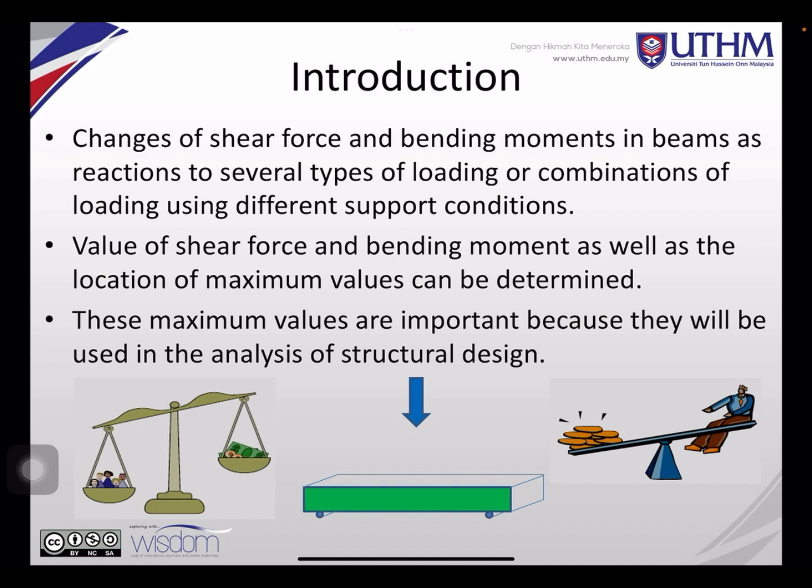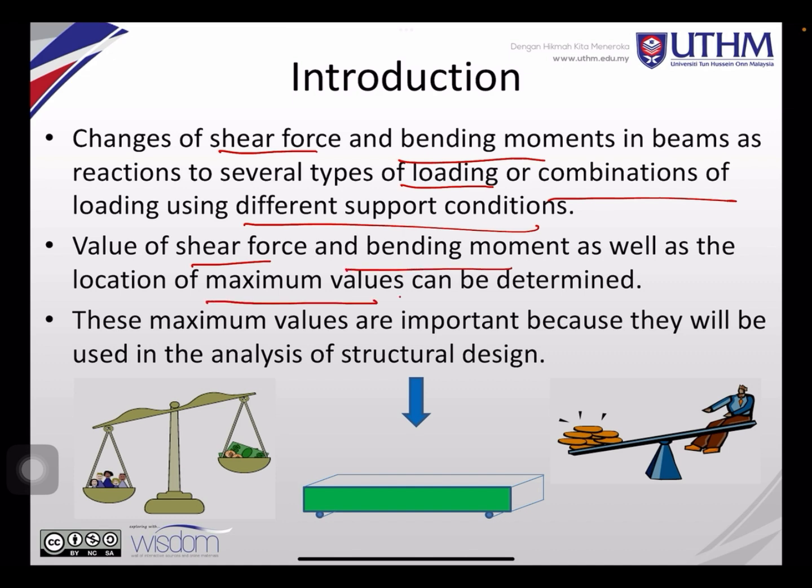So the shear force and bending moment in a beam change as reactions to several types of loading, including uniform distributed load, point load, moment, and so on, or combinations of different supports. You have cantilever, you have pin, you have rollers. The value of shear force and bending moment as well as the locations of the maximum values can be determined. This maximum value is important because it will be used in the analysis of structural design. We need the maximum values to know the maximum force and maximum reactions needed.